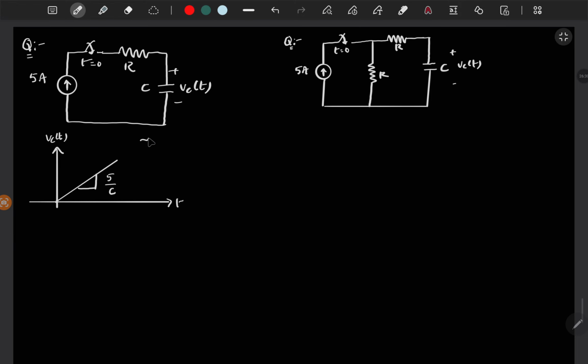And suppose if you want to find the time constant of the circuit, then for t greater than 0, since you have constant current source, just open circuit this current source and you will get c times the impedance across the capacitor terminals, which is infinite. So since the time constant is infinite, this will not go to a stable value, so it will keep on charging ideally.